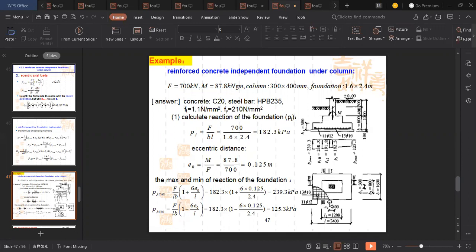Section 1.1 is cutting even the step. So the height of section 1.1 is from the bottom of the foundation to the top of the foundation, which we said is 800. Then section 3.3 is from the first step. Let me call it the first step. It's got a height of about 400. Then in this direction, we also have two sections. We have section 4.4 and section 2.2.